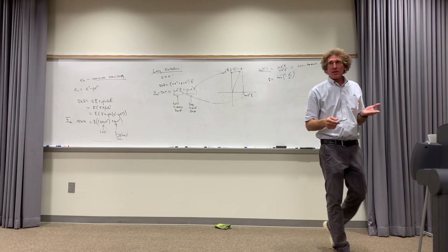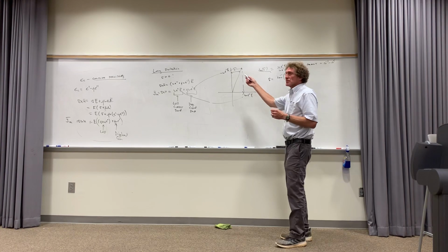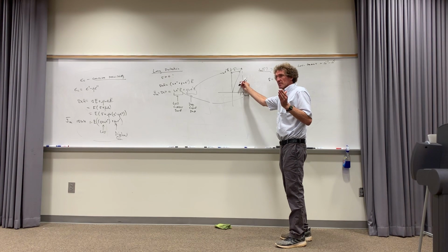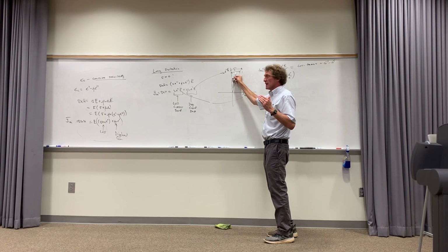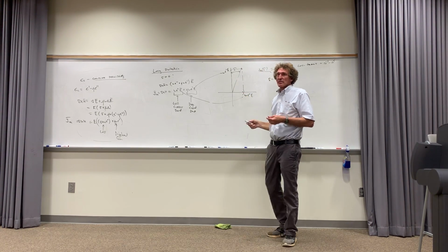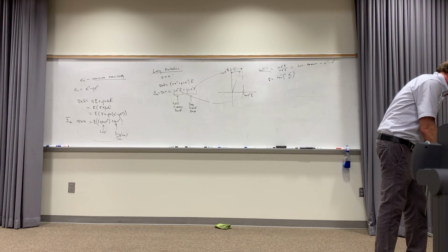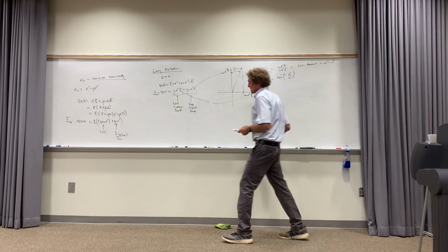In the back of the book, you're going to see loss tangent for materials. But it's a strong function of frequency. The higher the frequency, generally speaking, the greater the loss tangent. It's like the hands of a clock. At DC, there'll be absolutely none, if it's just polarization losses. Then as you increase frequency, all of a sudden, this hand starts moving out, out, out. And then it gets to a point where the losses become overwhelming, and it isn't even behaving like a dielectric anymore. Now, after that, we're going to talk about conductors. This is all dielectric stuff.